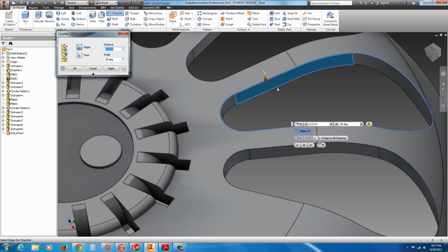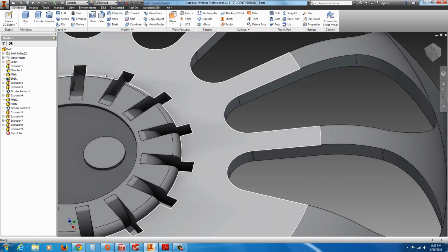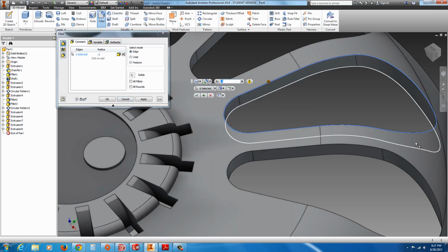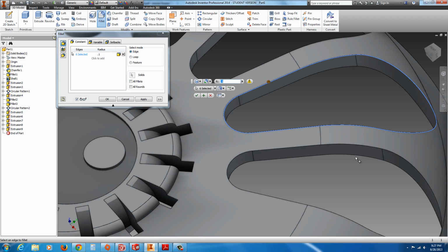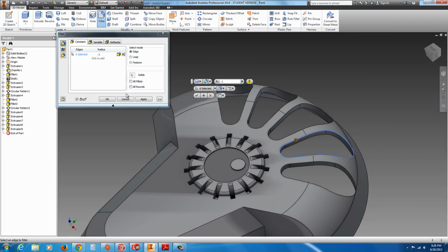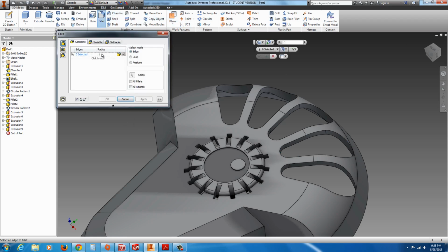If you don't see a preview, that's usually not a very good thing. Let's try putting a round on there. I think due to the complexity where it comes in contact over here, there might be some issues, and we're getting little error messages there. Oh, actually, that was just set very high. Hold on a second. So 0.01. There we go.